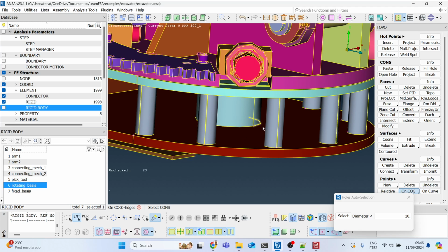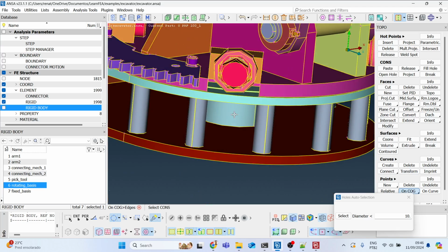To select this whole circle, you can use this tool, loop. Activate it, and then position the mouse here, and you see that it already selects the whole circle. Select it, middle mouse button, and then one point was created right in the middle of that circle.